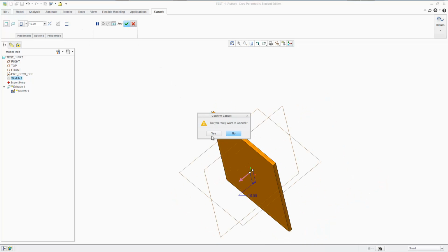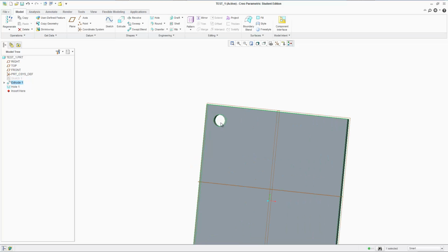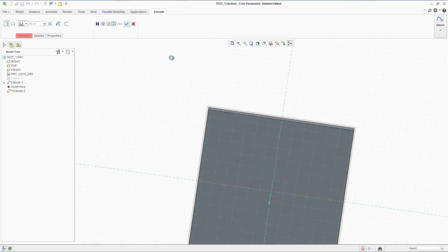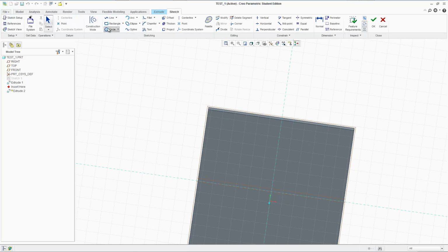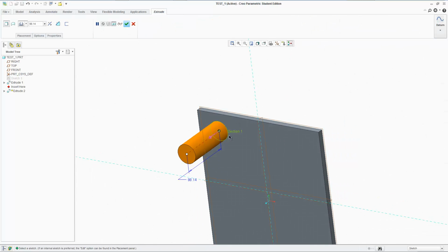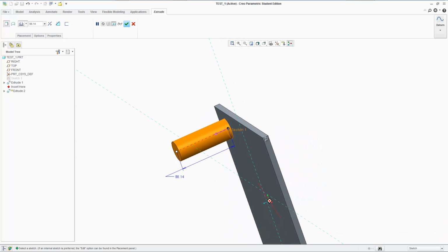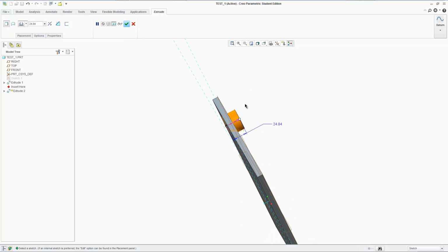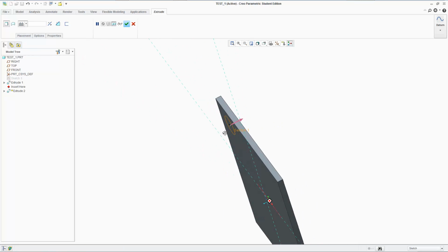There's another thing. That's how we made the hole, and that's how you should make holes. But if you're just making a round drilling thing that you want to drill, there's another way to do it, and it's essentially removing materials using the extrusion command. Let's just make a circle here. So like any extrusion, you make a sketch on a plane or on a surface, and then you say extrude. But this time we want to go in that direction, and we're going to select this right here so it goes exactly the distance we want it to go.